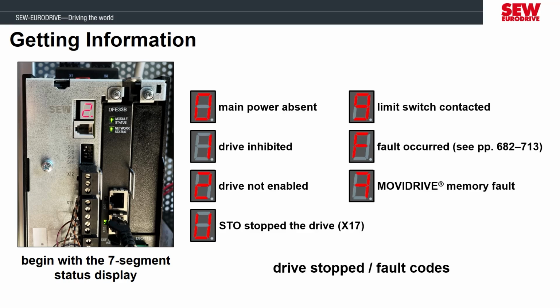If you need a refresher on the voltage and digital input and output locations of the MOVIDRIVE and the purpose of each plug, then you can go back and watch the video for session 2 to learn about those. You should know the purpose of the connections since some are 24 volts and other ones have in excess of 700 volts. Never disconnect any of the connections while the MOVIDRIVE is powered because it can cause an electrical arc.